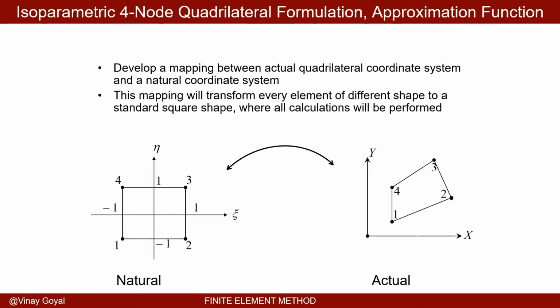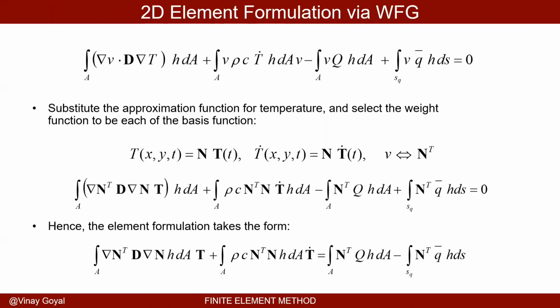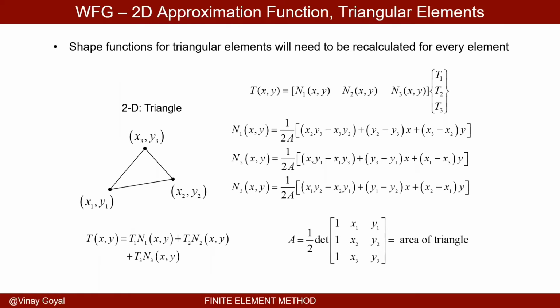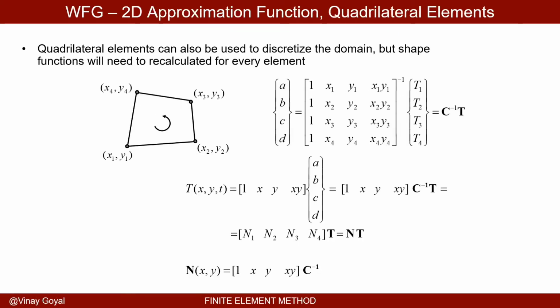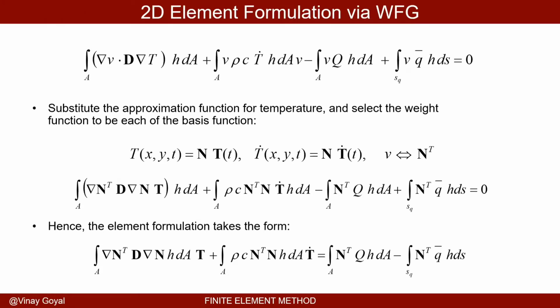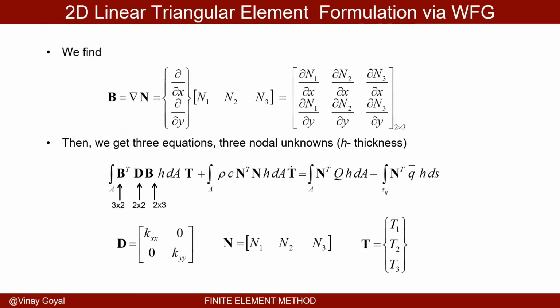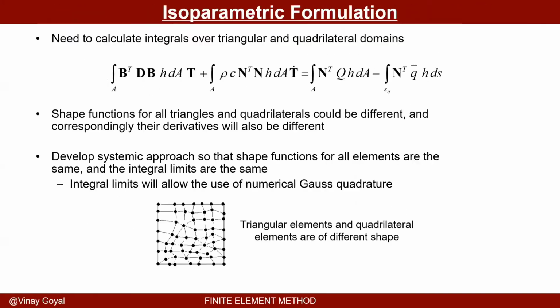So what is the goal? What we want is an approach, a solution to this problem that I just discussed, because you can see here that every element is going to have different shape functions. We don't want that. We want something simpler. You can also see that every quadrilateral element will have its own shape functions, and the integrals that need to be calculated are over an arbitrary domain, and every element will have its own domain.